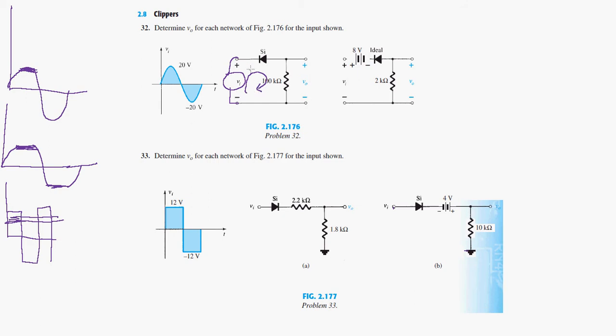And so if you look here, this diode, when the voltage is positive, is reverse biased, because we have the positive voltage on the negative side. And so for the positive part of the wave here, this diode is open. So it's an open circuit, so the voltage here will be 0, because we are only taking one side of the voltage source. So if we sketch the response of the circuit here, for the first part here, the response will be 0, there will be no voltage.